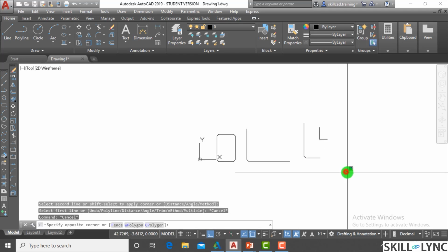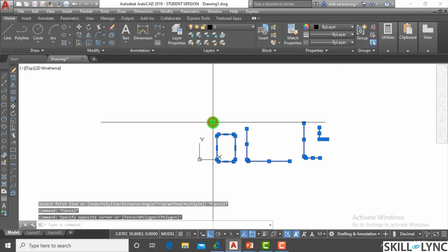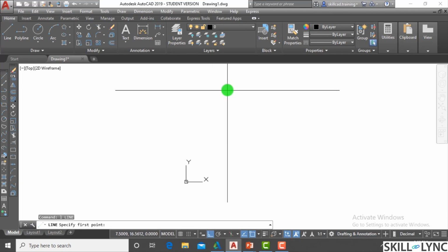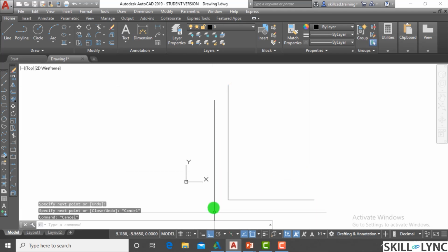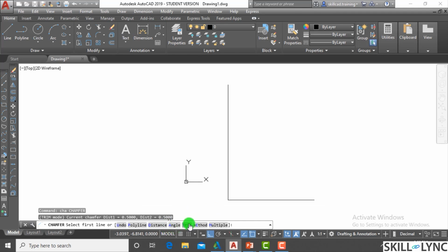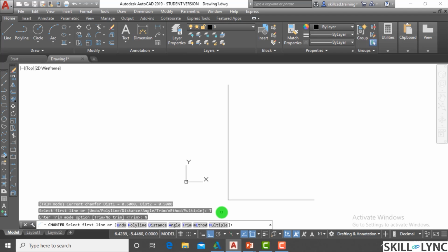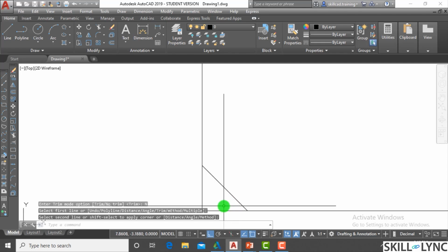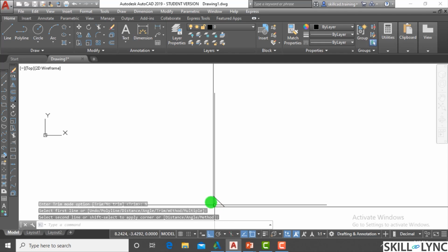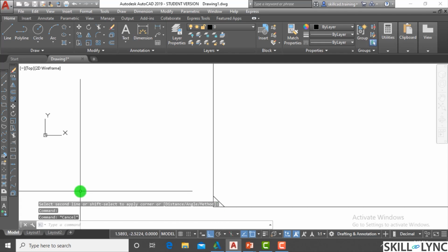Now what I talked to you about, a tip shortcut where I am going to join the objects, right? But let us take the trim option. It is similar to what is there in the AutoCAD fillet tool that we used just a few minutes back. So if I use the no trim option, and I take a distance, let's say 0.5, 0.5. So again, the corner line will remain over here as it is, and a chamfer line will be created. Chamfer line is an individual line, right?